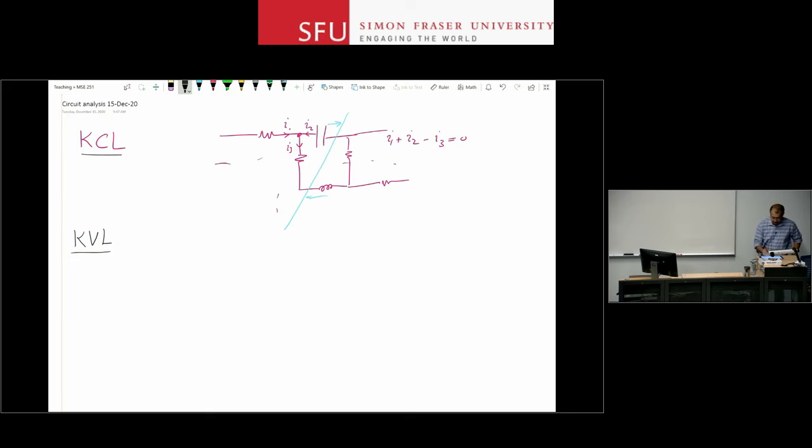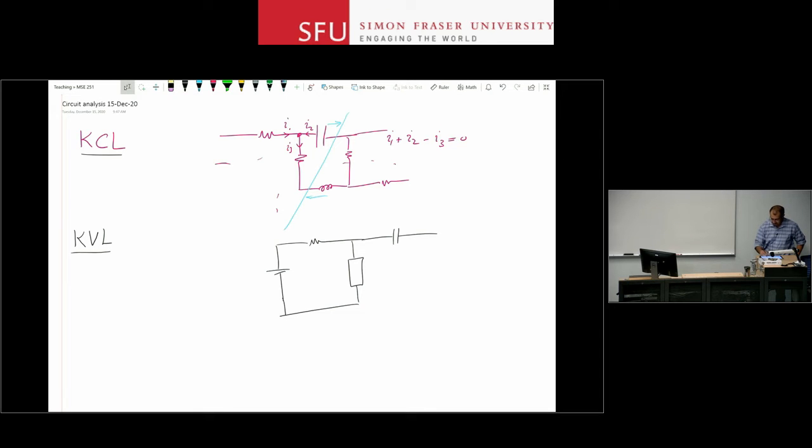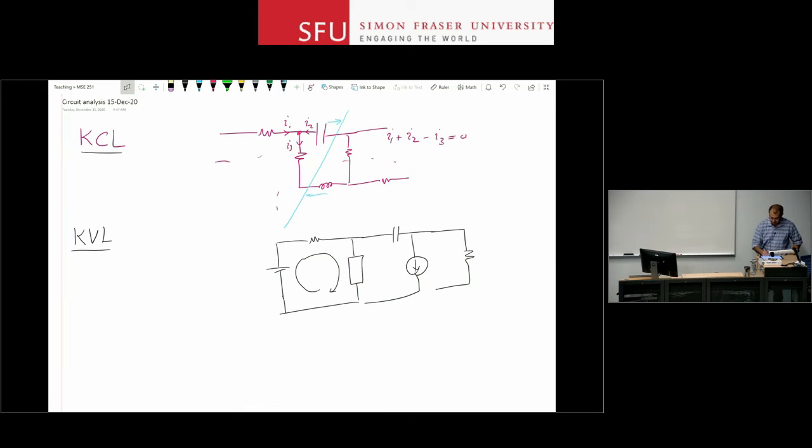And this is different. This says that if you have a circuit of whatever complexity, linear or nonlinear, and you find a loop, if you go around the circuit and come back to the same starting point, let's say this, and let's put the current source here, and a resistor here, right? A circuit like this has many loops, but if you take any of these loops, it could be this, or this larger loop, and go around that loop and come back to the same point, the sum of the voltages that you have is going to be 0.